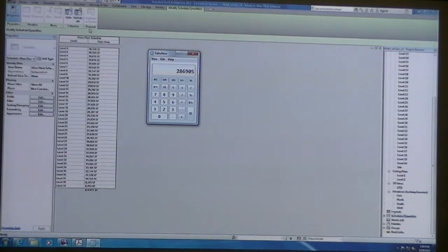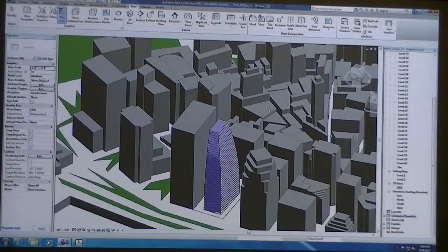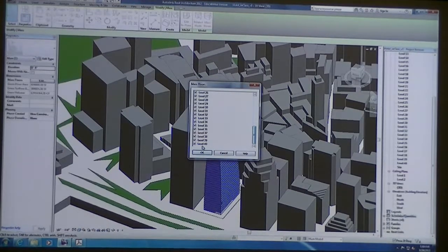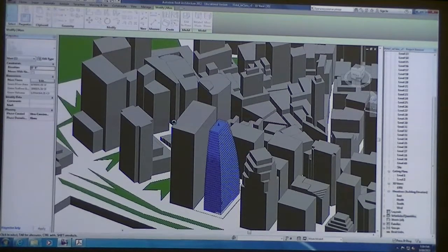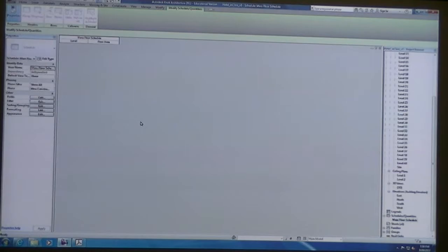Now that we have this floor schedule calculating all the floor areas, you can go ahead and start modeling and massing an idea for your hotel using the same techniques and creating your own mass floor schedule for your hotel instead of that zoning mass. You might just write down this number, 875,000 square feet, so that we can get rid of all of these mass floors on the zoning mass. I just did that as a quick example to go through those steps again. And you will notice that as I remove those, I no longer have a mass floor schedule.